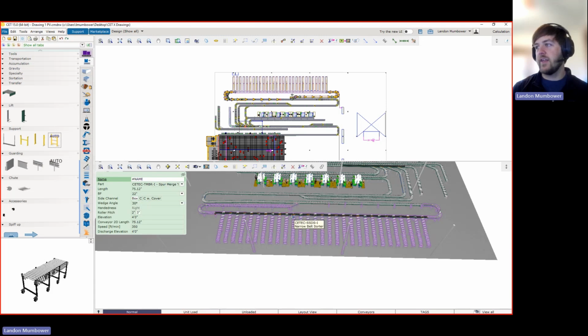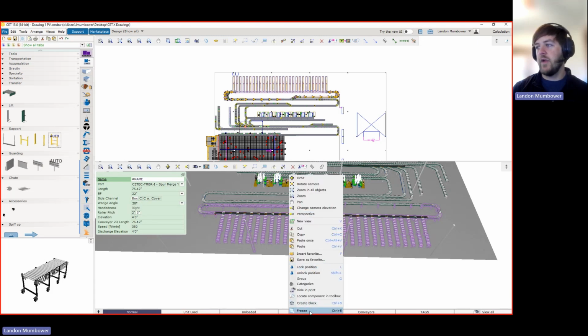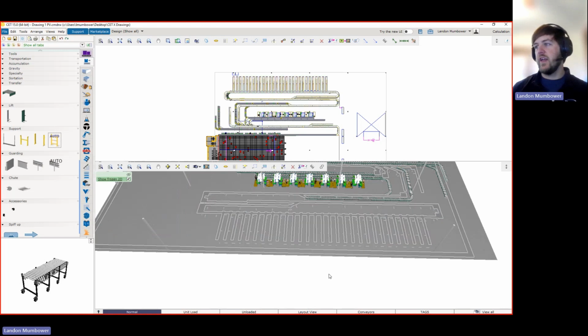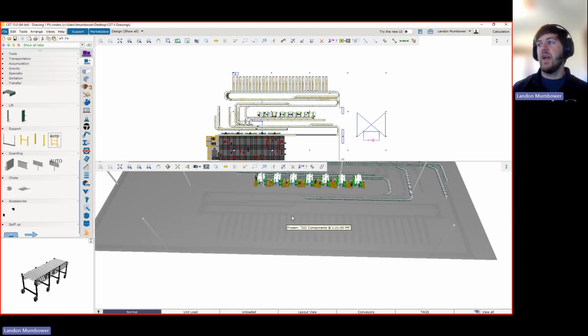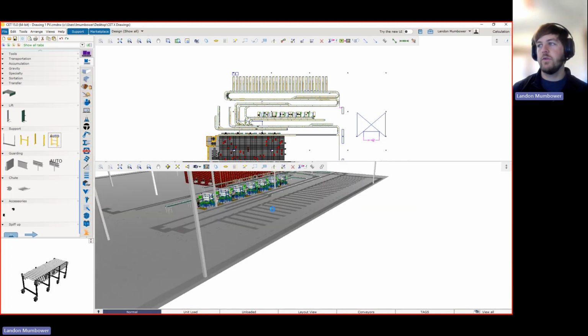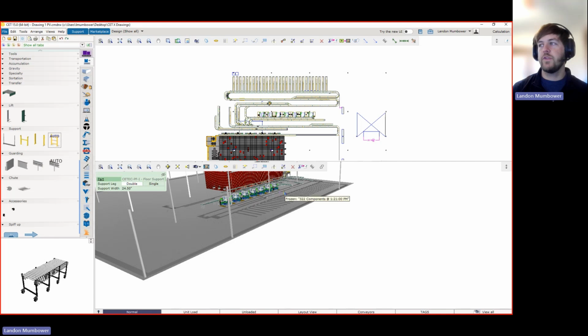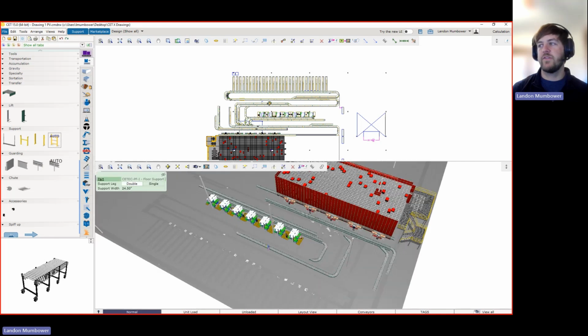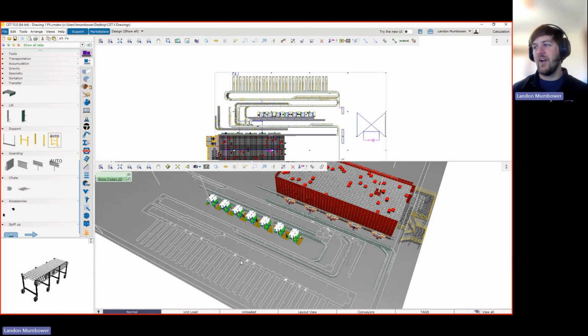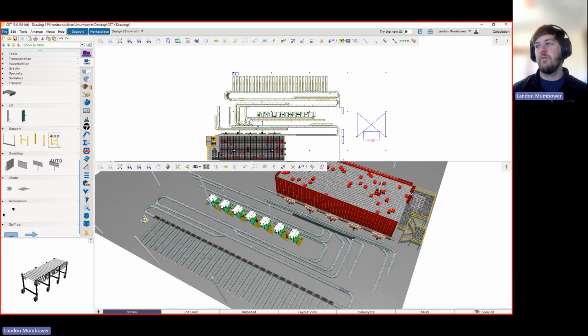And if I right click on it and go down to the bottom, I can click freeze, or you can press Control E for the keyboard warriors. So hit freeze, and now that is frozen. It's there. It's not going to load in, so that is something to keep in mind with freeze, but it's also not going to get messed up. So, I mean, it's technically gone through and frozen all of the conveyor here in this example because it's all connected. So sorry for that little mishap when doing this, but now I can just come and find this, hit unfreeze, and now it's back and we can mess with it.